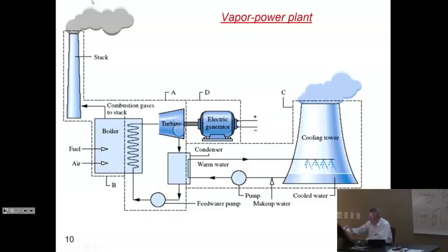The rest of the steam comes out of the turbine, goes to a condenser, which is actually where the heat will go out. This is where the heat goes in, hot side heat in, cold side heat out. And then the water is condensed, so it's liquid water here. It goes through a pump, which increases its pressure again, and then it goes through the combustion.